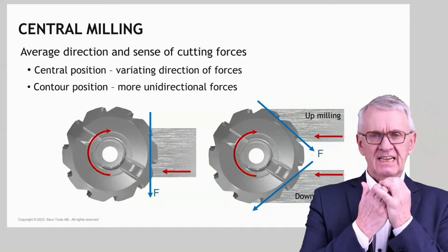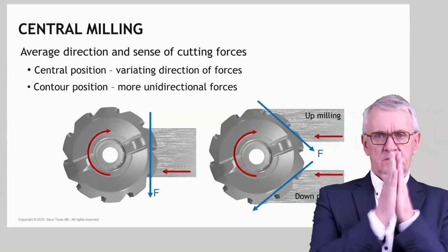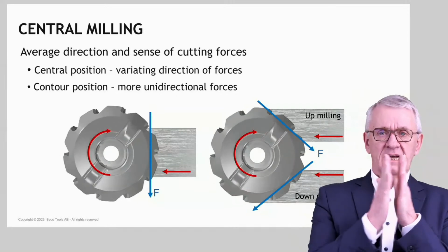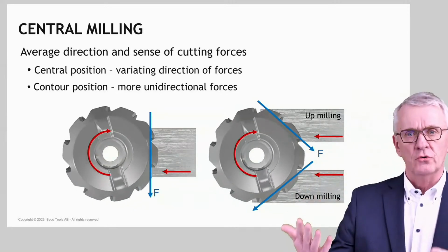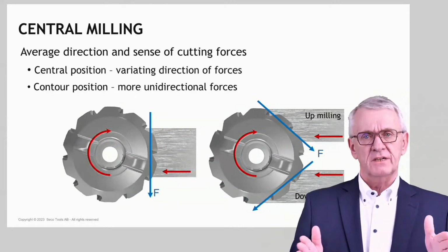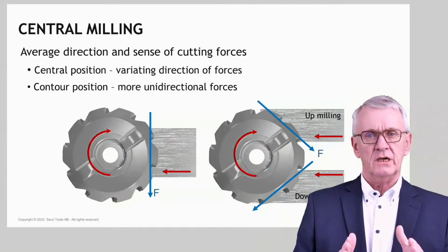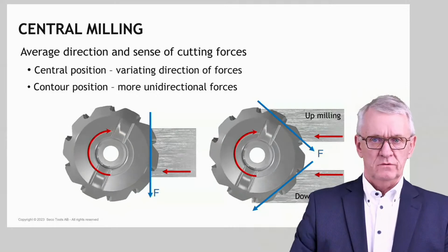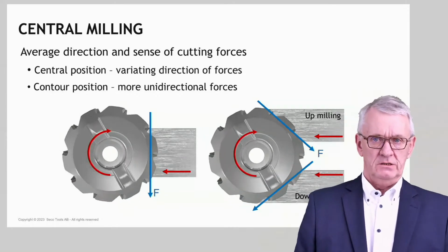And that can create a situation where milling cutter and workpiece start to do this. As I show it here, it's a bit overdone. But this situation, where you start to have a relative movement of milling cutter and workpiece compared to each other while the milling cutter is moving forward, potentially leads to micro vibrations.